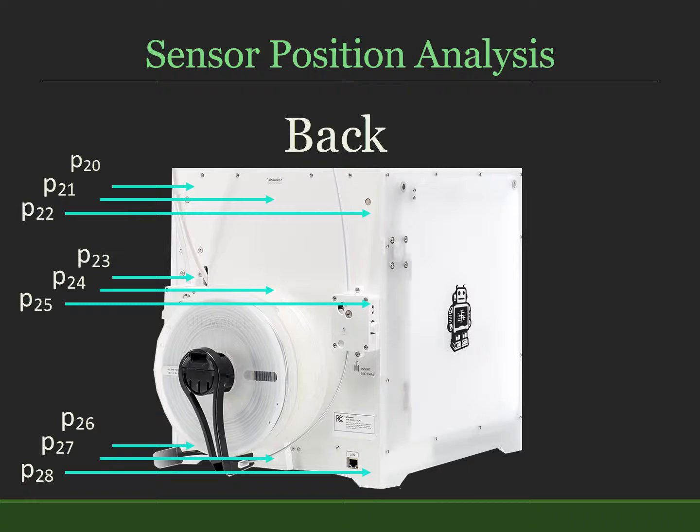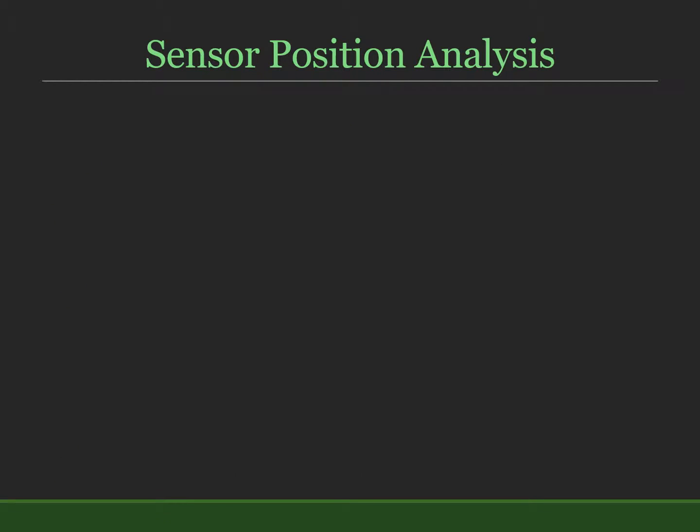For each position, vibration, acoustic, and magnetic sensors are placed and data is collected for various digital twin product parameters. Then, a gradient boosted random forest is used to create simple classifiers to estimate the accuracy of the model based on various sensor location data. The classification accuracy is used as a metric for determining the placement of the sensors around the 3D printer. The digital twin product parameter selected for estimating the classifier consists of simple G-code instructions such as presence or absence of stepper motor movement in the X, Y, and Z axis respectively.